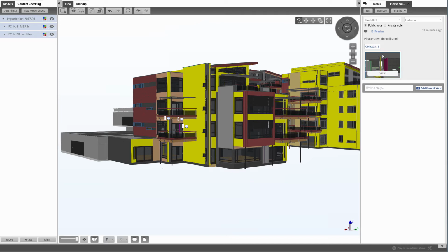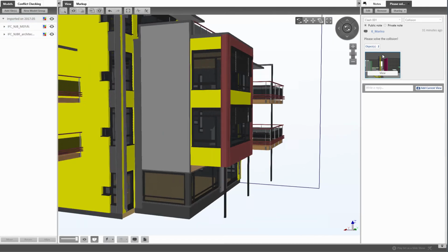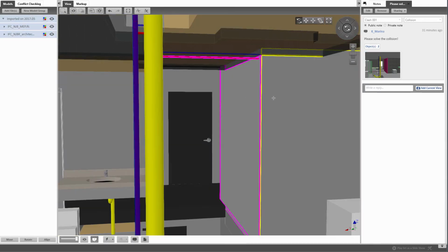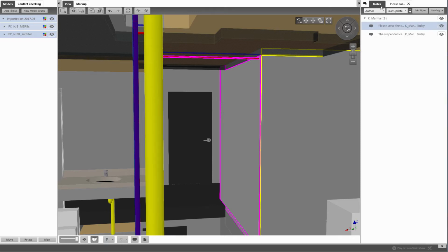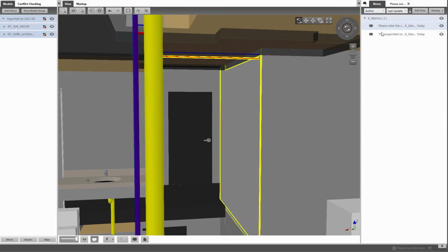By double-clicking on the image, BIM Site sets the same model view as if it was set at the ARCHICAD markup's definition. They do this by rotating the view to the exported camera position and by adding clipping planes with their position stored in the BCF file. Clicking on Objects selects the pipe and wall objects assigned to the markup entry.